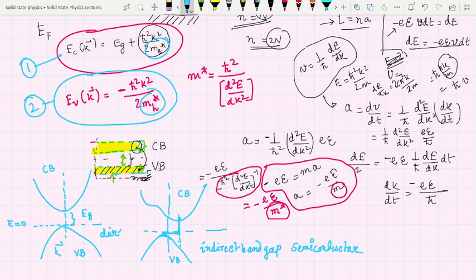So gallium arsenide is preferred as the constructing material for LEDs because energy dissipation is very low here. That's because it is easy to excite the electron from the top of the valence band to the lowest point of the conduction band, whereas a little more energy is required for the similar transition in the indirect case. These are the things that we can get from the band theory.